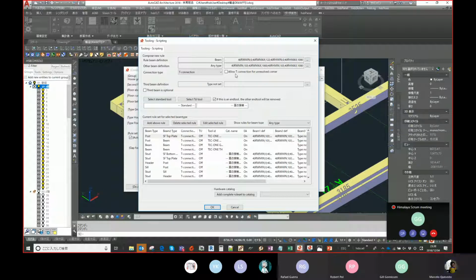Well, for instance, yes, but in some case I guess they could split beams of this type with these dimensions, if you want to split them. But there's more logic to splitting, right? You have a wall, you have a window, they have a post over there, so you will not split it at that location. That type of thing is really a manual approach. The purpose of this function is to be able to draw 95% of your construction extremely fast, and then you need those manual modifications that you're not able to automate.